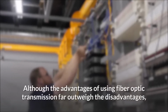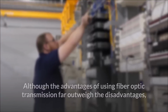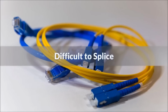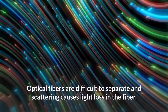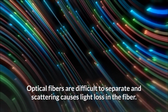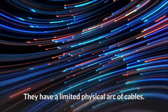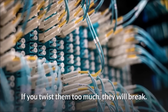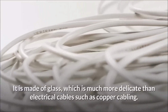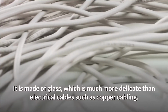Although the advantages of using fiber optic transmission far outweigh the disadvantages, its disadvantages should not be underestimated. Difficult to splice. Optical fibers are difficult to splice, and scattering causes light loss in the fiber. They have a limited bend radius. If you twist them too much, they will break. Fragility. It is made of glass, which is much more delicate than electrical cables such as copper cabling.